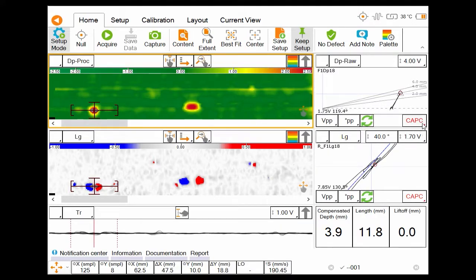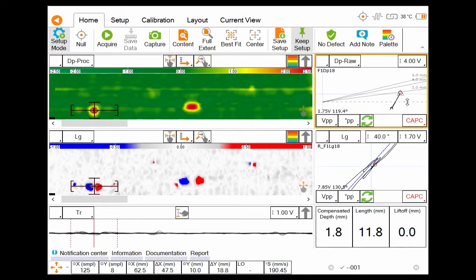As I press this button here, the software, as I explained, will move the cursor on the channel with the highest or the deepest measurement. And by default, it's going to propose a baseline here in the Lissajous view. If you want to adjust or fine-tune the position of the baseline, a power user could do it pretty easily. After that, we also add in this Lissajous view some depth curves. Once we define the baseline, depending on the amplitude of the defect, we reach a different depth line, which are all identified here in the Lissajous view. So that makes the analysis even simpler.